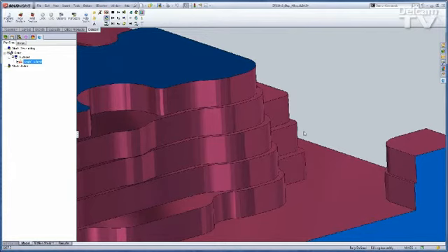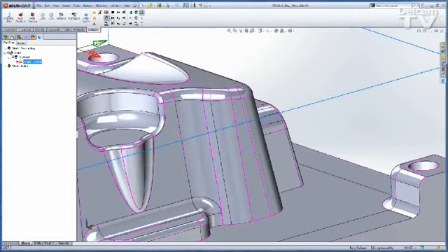There are a couple of ways I could approach this. I could use multiple roughing diameters, or I could generate a stock model from this result and add another Z-level rough process using that stock model. But in this case, I'm going to show you step milling.